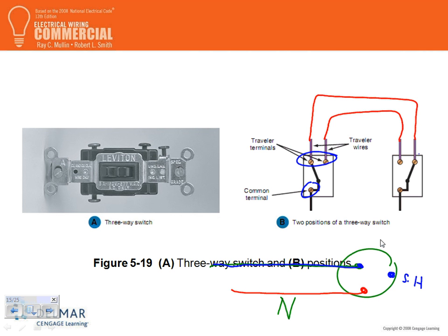So I have my neutral tied. These two are for the fixture, terminal for the fixture. This is just a terminal, a wire now. How do you connect now to turn this light from two locations? How do you connect? Which side do you go? Does it matter which side? Okay, you're going to tie this system to this. There's power coming to the fixture, and there are two 3-way switches connected together. You're going to wire it. How do you wire this?